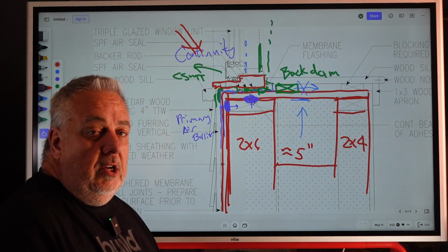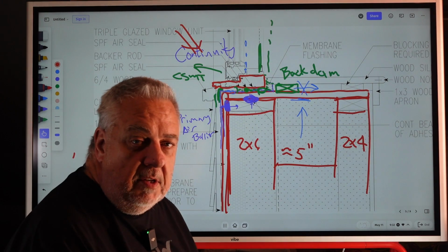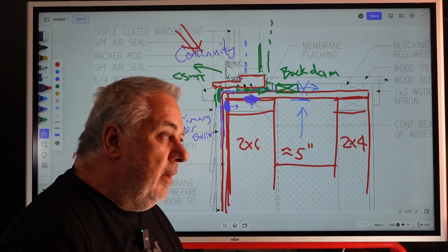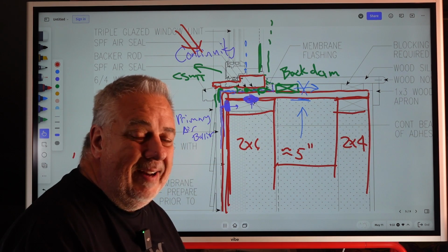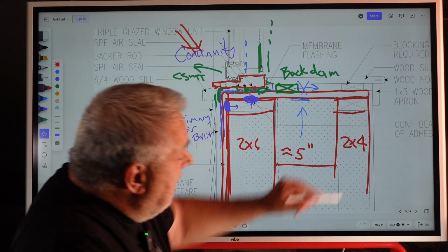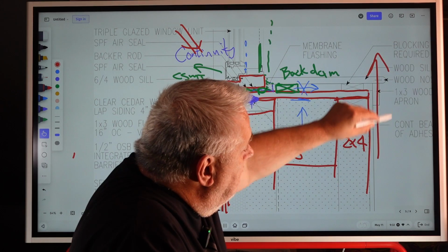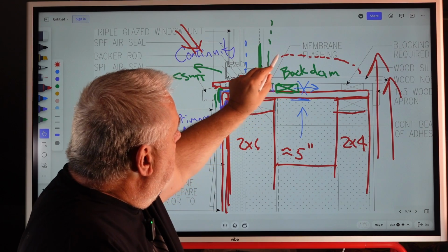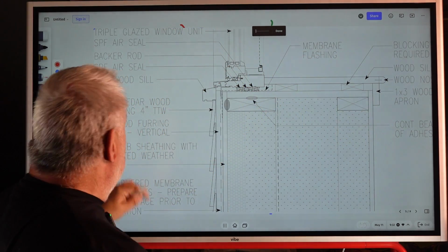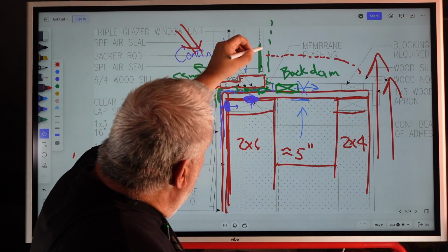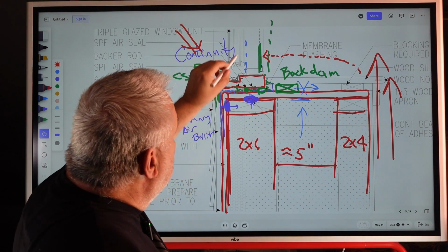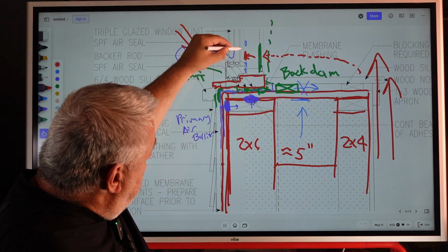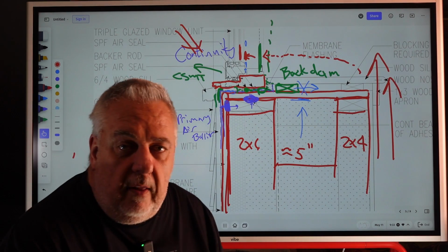The one risk that I do have is if this is a relatively small window and I am in an extremely cold climate, I mean, maybe climate zone 5 could have some bad days, but definitely climate zones 6 and 7, I get that heat rising or delivered from the floor and it doesn't really get all the way in here to warm that inner surface. Oh, it's right there actually. That inner surface of the glass.